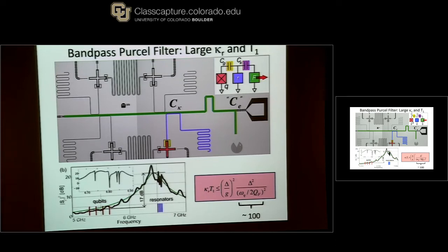So the whole point of this resonator, dispersive readout, is to act as a filter so that at the qubit frequency, you separate out the damping from the measurement frequency. And then the measurement doesn't affect the qubit operation so well.